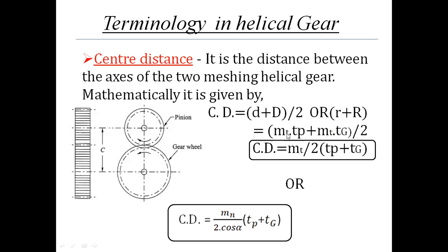So d in terms of teeth: mt into teeth on pinion plus mt into teeth on gear, divided by 2.